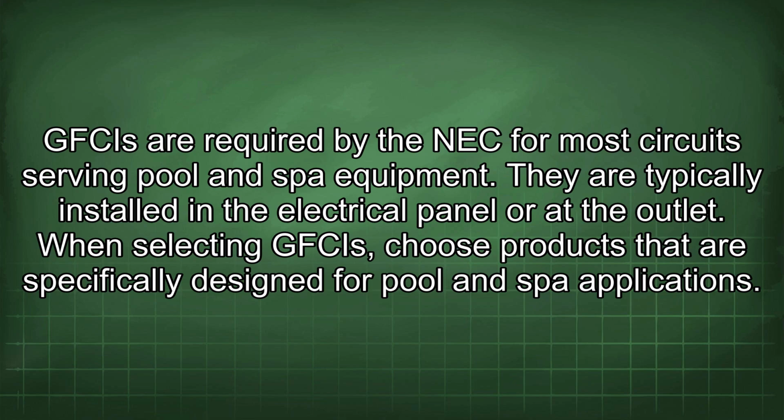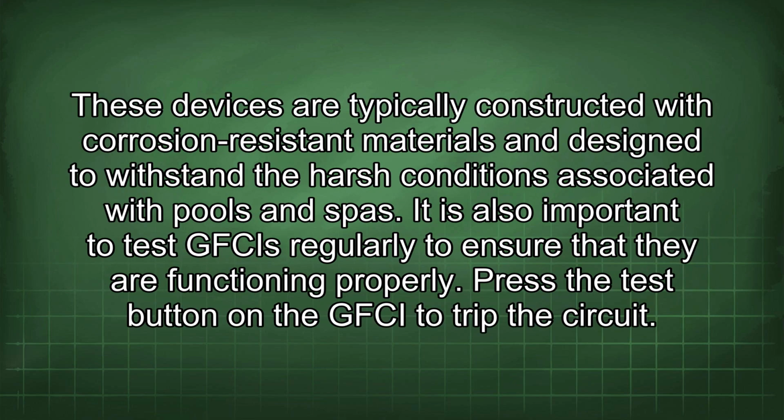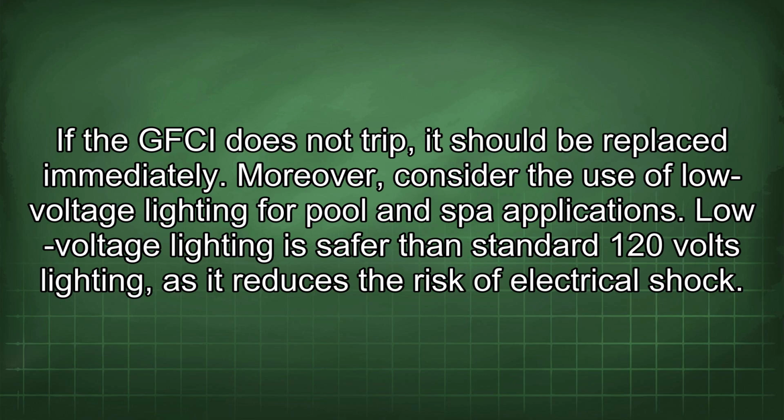When selecting GFCIs, choose products that are specifically designed for pool and spa applications. These devices are typically constructed with corrosion-resistant materials and designed to withstand the harsh conditions associated with pools and spas. It is also important to test GFCIs regularly to ensure that they are functioning properly. Press the test button on the GFCI to trip the circuit. If the GFCI does not trip, it should be replaced immediately.